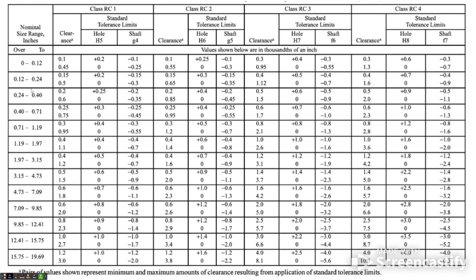For example, if we had a 5/8 pin, we would come down here, and 5/8 measures 0.625, so it's going to be at this one. We would then come over and read through the chart depending on which class of fit we would want. And then we would apply that to both the hole and the shaft once we calculated and did that basic math.